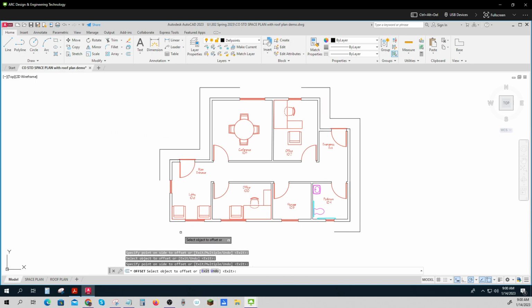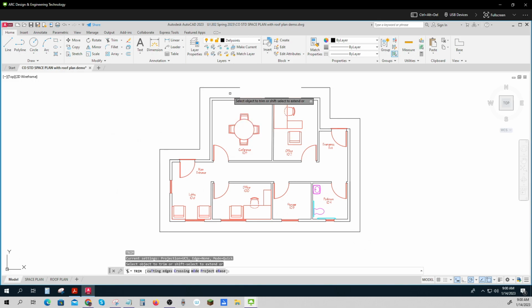And that's actually probably enough because I think I can do a fillet command with a radius of 0. I should be able to fillet this one and that one. Oh, that one worked. And then maybe I can do a trim and do that fillet again to connect these two. And that gives me a nice, quick, and easy roof to work with. So those are my eaves.